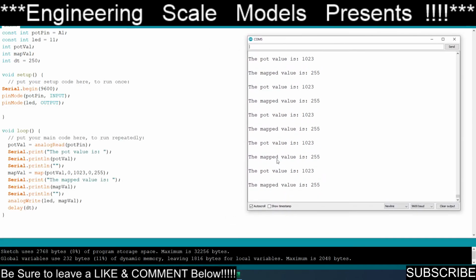We can see this. Now you see that every quarter second, it's reading the value, it's mapping the value, and it is printing the value of the map value, and then it's writing to the LED, and it changes in pretty much real time with the turning of it, because it only has a quarter second delay.